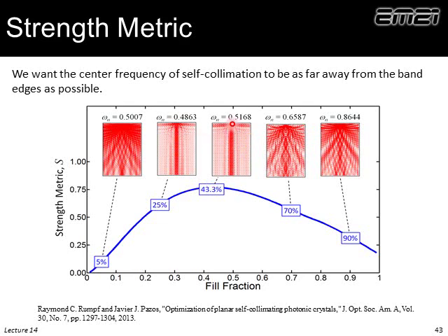How we generated these, we had a little dipole source, which should radiate in all directions, but due to self-collimation, it radiates in all four directions. If you want pretty self-collimating pictures, that's the worst way to simulate a lattice. But we like it because if there's anything wrong with the lattice, this will spill it out. If you want better pictures of self-collimation, you would have a much wider beam. But this does confirm we want that inflection point away from band edges. So I mentioned before, the inflection point isn't necessarily the frequency where the best self-collimation occurs.